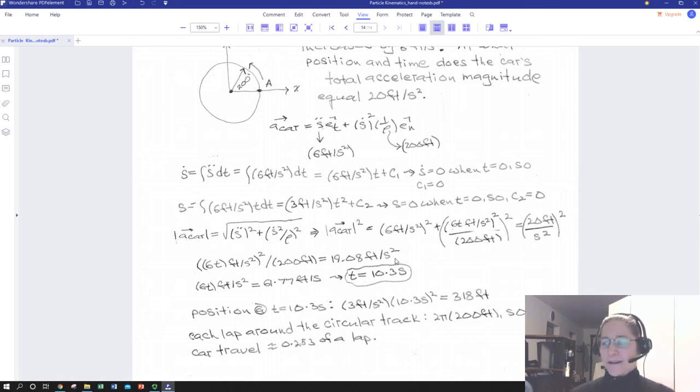We could just remember it as a radius of curvature expression instead of an r in our normal component, and know that our tangent normal expression for acceleration and velocity will be the same as polar anytime we are constraining ourselves to follow a circular path. So if you get presented with a problem and you're not sure whether to use polar or tangent normal, just write an expression for your path and use either system.